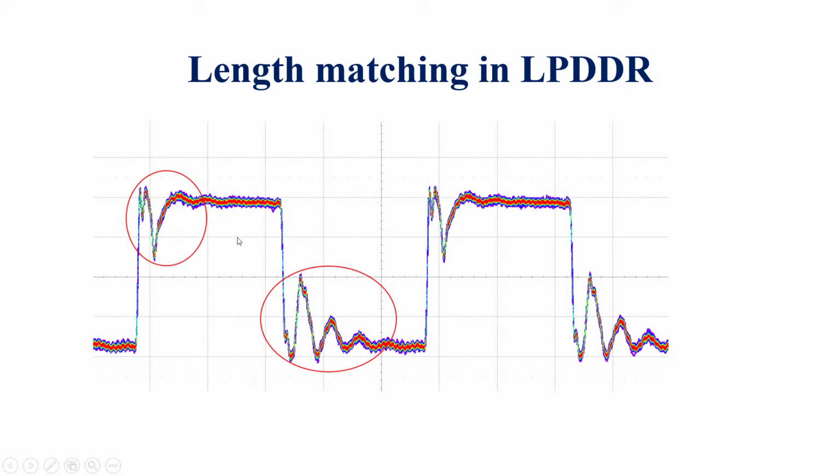The single-ended, high-speed signal in this design can be analyzed by using the signal integrity single-ended track analysis. In this, the clock signals or the high-speed signal traveling from source to destination will appear like this. A reflection will appear like this. By providing series termination, it can be solved.